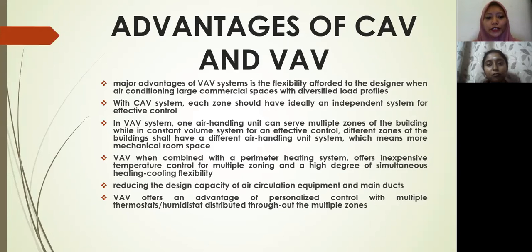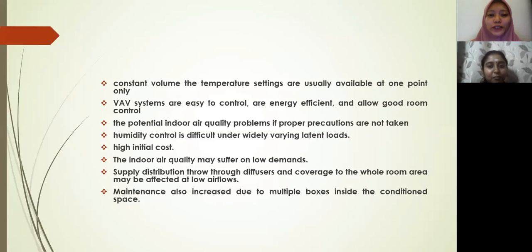It reduces the design capacity of air circulation equipment and main ducts. VAV offers an advantage of personalized control, with multiple thermostats and humidistats distributed throughout the multiple zones. In constant volume, the temperature settings are usually available at one point only. VAV systems are easy to control, are energy efficient, and allow good room control.